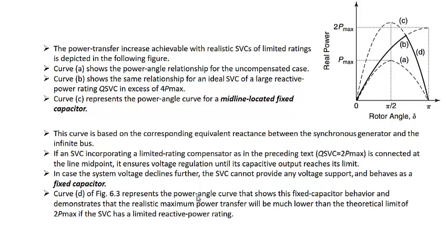So that is why we will only discuss this fixed capacitor arrangement of the SVC, because practically it will mostly be used in the capacitor range. After its limited range, it will act as a fixed capacitor. So curve D in this figure is this one. Curve D represents the power angle curve that shows this fixed capacitor behavior